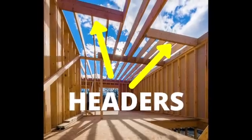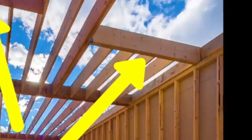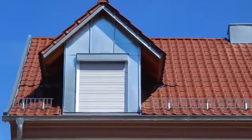Just like a small girder, a ceiling header carries the weight of several joists by transferring their load out to other parallel joists. This lets you create openings for pull-down attic stairs, dormers, staircases, you name it. So that's a second definition for headers, and it serves a slightly different function. These headers are installed in horizontal floors as opposed to vertical walls.